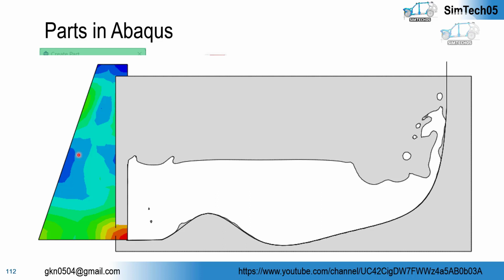When we have large deformation and element deformation may be problematic for us, then what can we do? We can simply utilize the Eulerian domain, so material flow can take place within the elements. Okay, so that is completely different. Here you can see this bounded rectangle is nothing but your Eulerian domain, and this wide region is representing sloshing of the water. Okay, so water is sloshing within the Eulerian domain.